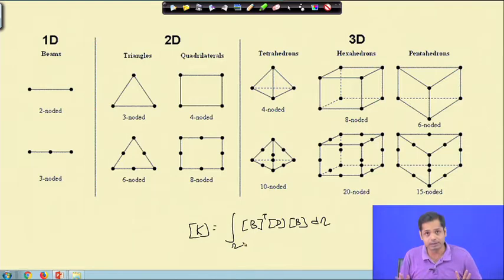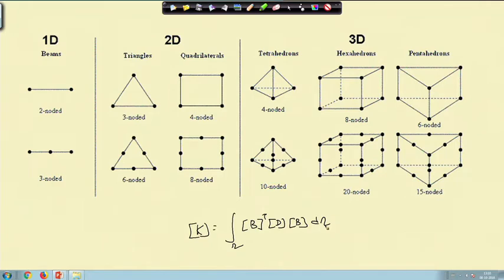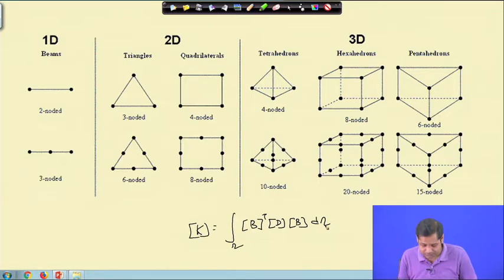The details of the isoparametric element we have not discussed, but we mentioned that if your elements have different shapes, we can always have a map between a square or rectangular element defined in a parametric space and the actual space. Then you can construct your shape functions and do the integrations on the parametric space, keeping the map between the parametric and the actual space preserved. So this is the stiffness matrix, and similarly in the load vector you also have an integration, if you recall.